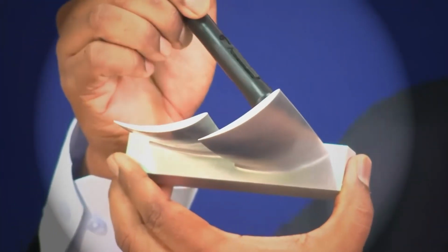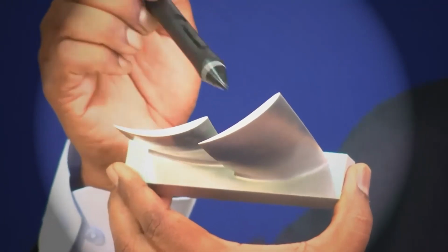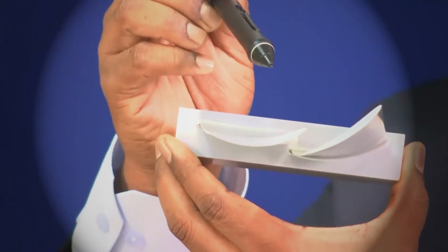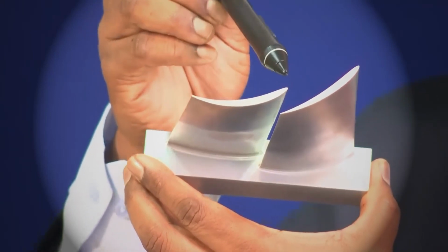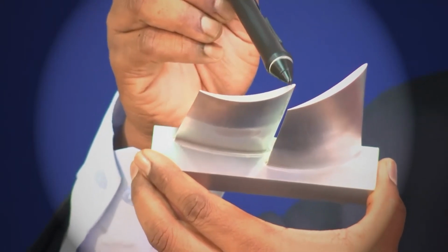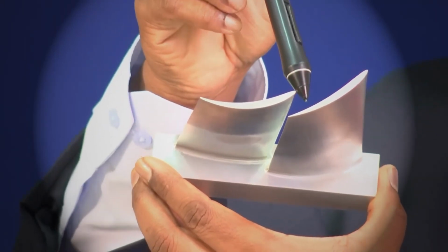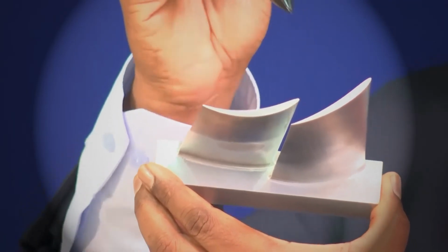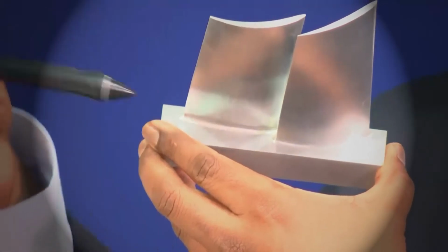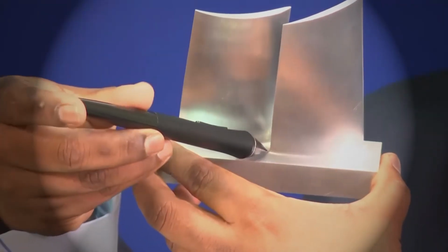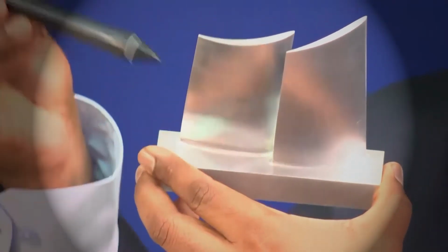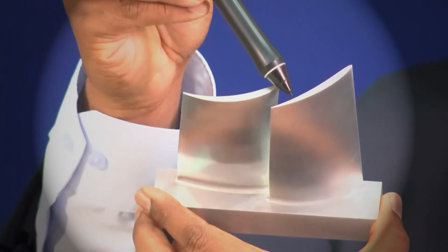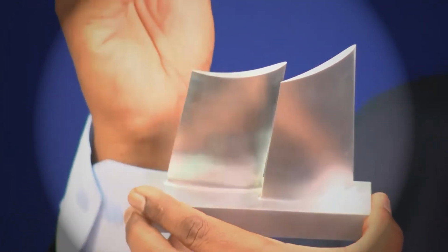This aerofoil has been stacked about the CG, and if you look carefully, our axial overlap is varying. If you measure your distance, this is my axial overlap. Near the hub region, my axial overlap is 0, and here it is 3%.